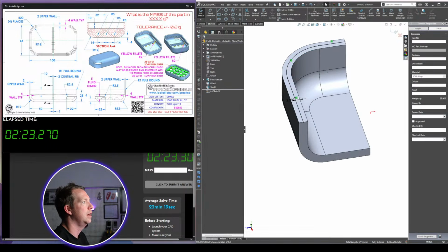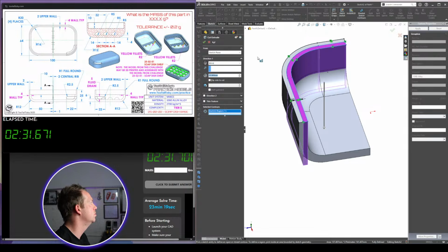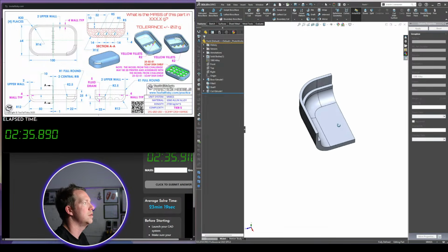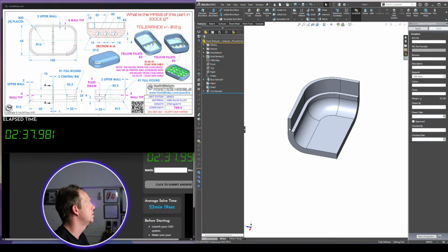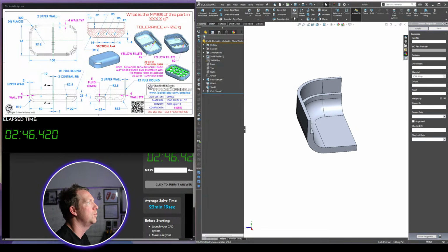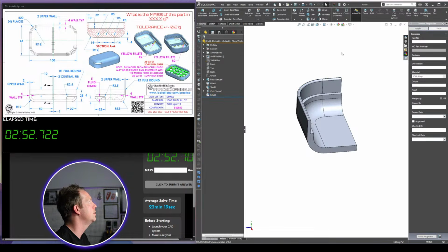Then I'm going to convert the whole thing and then cut down by selecting this contour and selecting the distance to 10. Alright, so there's my little ledge. Now it says there's a full round fillet on the top, which is a bit hard to see, but we'll put that in, which just means a 1mm fillet on both edges.